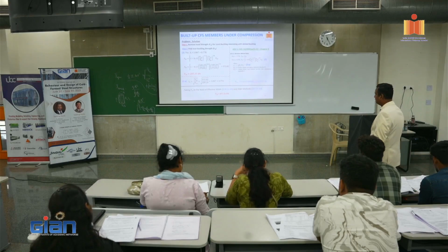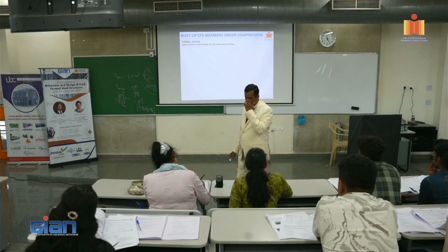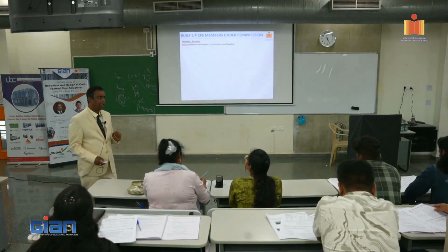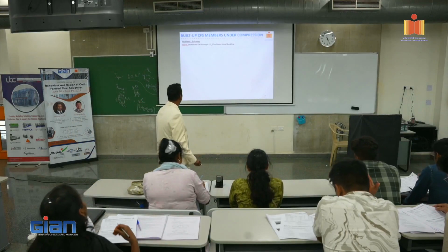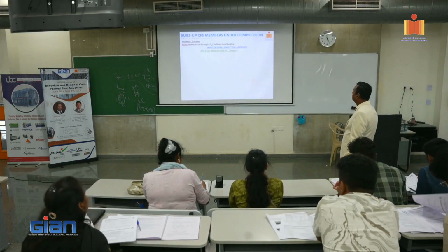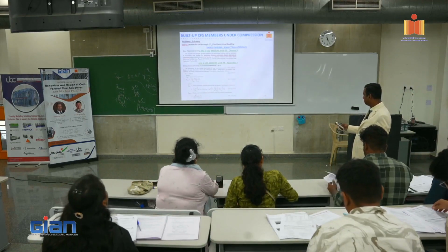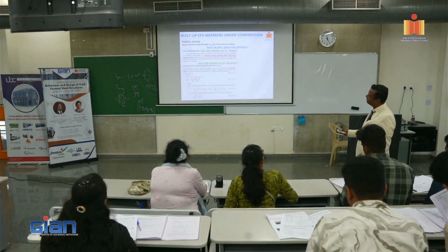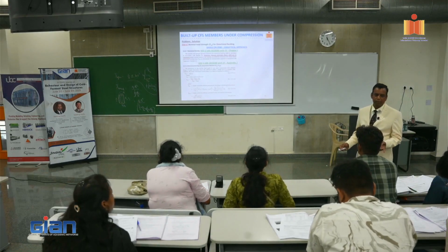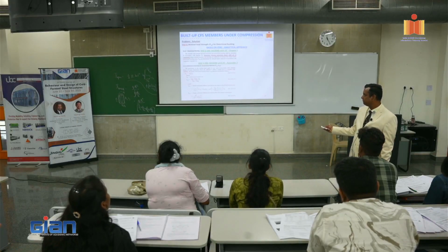The third one is your distortional buckling strength. Distortional buckling strength calculation is a little nasty. You have to do a lot more calculations, based on the DSM analytical approach. So this is chapter 1. You have to take all these things into consideration. It gives a lot of equations. It's very simple if you look at it. What is PCRD? You have to calculate PCRD. Why should we calculate PCRD? So that we get lambda. So we need PCRD. But PCRD is given as AG into FCRD.